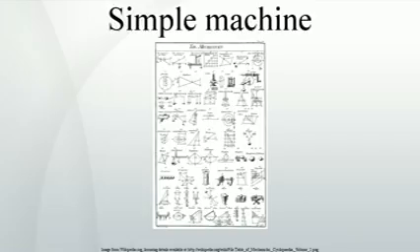So in non-ideal machines, the mechanical advantage is always less than the velocity ratio by the product with the efficiency E. So a machine that includes losses such as friction, deformation and wear will not be able to move as large a load as a corresponding ideal machine using the same input force. The efficiency of a compound machine is the product of the efficiencies of the series of simple machines that form it.